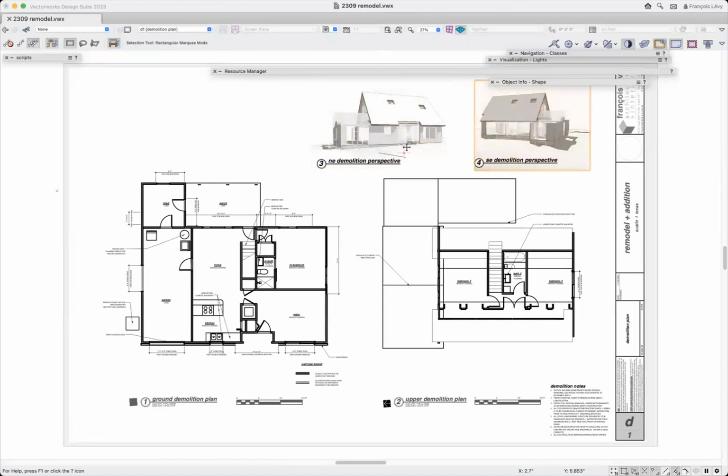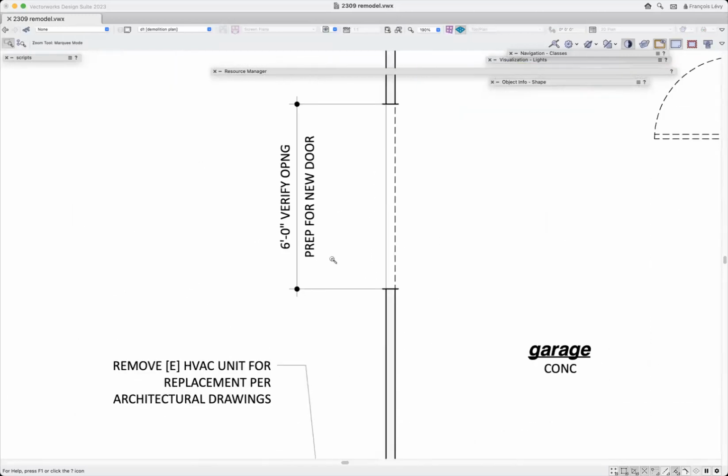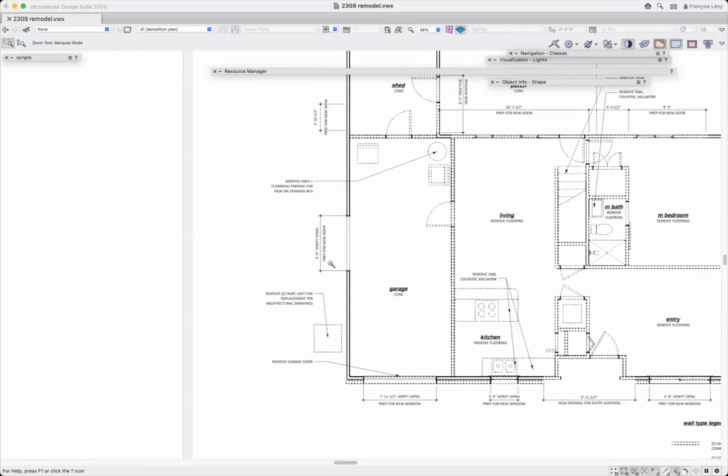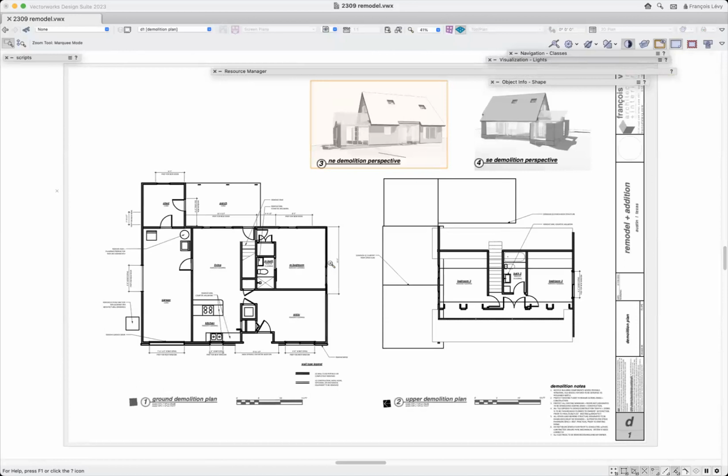Yeah, but these little model viewports, the model's there. I could easily have not just a demolition plan, but demolition elevations where we call out the heights of openings and where they occur. For a project of this complexity, that probably would not have been a bad idea. Because when you do that level of demolition, a plan alone is not sufficient. It's not really enough to say, make this 6 feet or 6'4" or 6'6". It'd be nice to have a height. That's not that hard to develop from this sort of workflow of having existing versus new construction layers, and then demo classes, or data visualization and demo record formats.